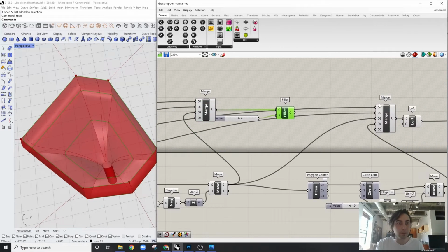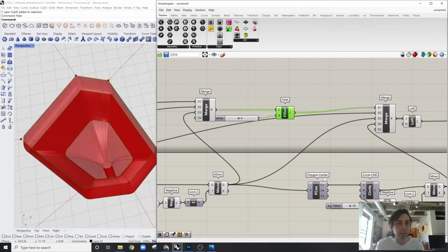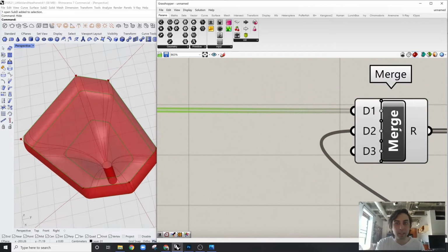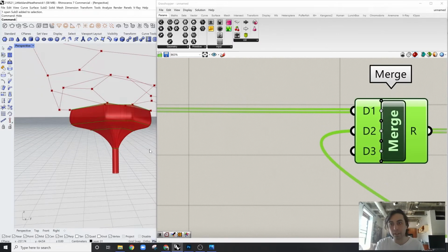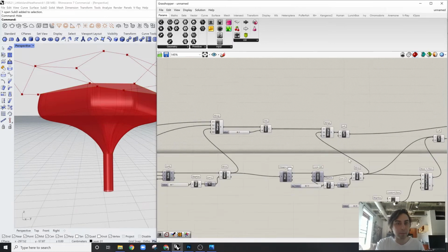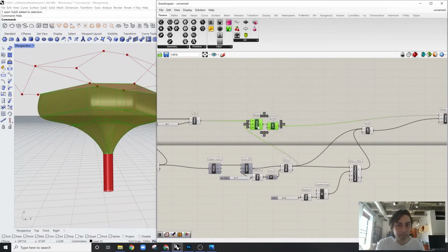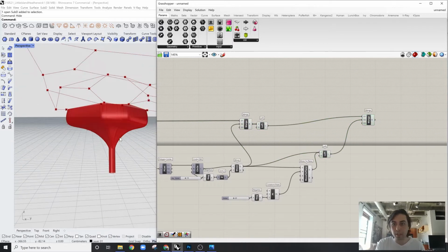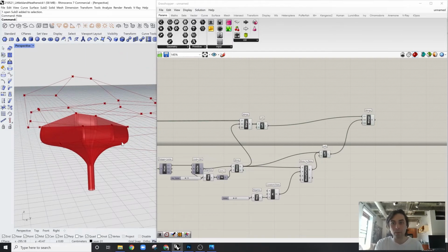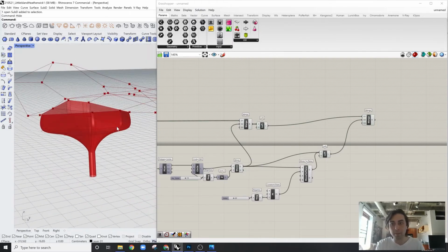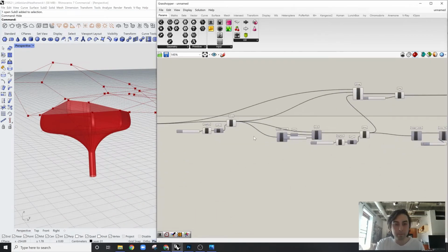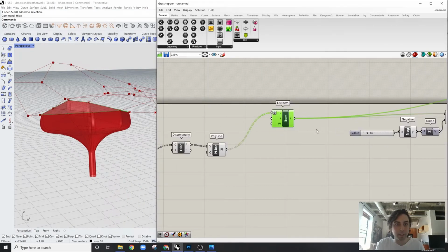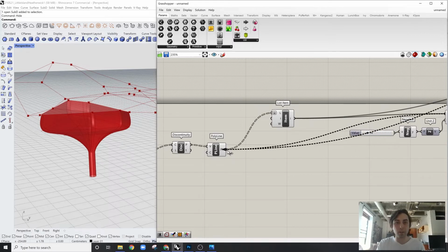Now we're going to have each one of those, and then I'm going to just go in here, replace that, and then delete. So now I have those 3 filleted curves, bringing in the circle at the end before you loft it. And then the second loft, and then the merge. Okay, so let's see what actually happens when I replace this. This spot needs to be gone, so Control Shift and just plug all of these guys into here.